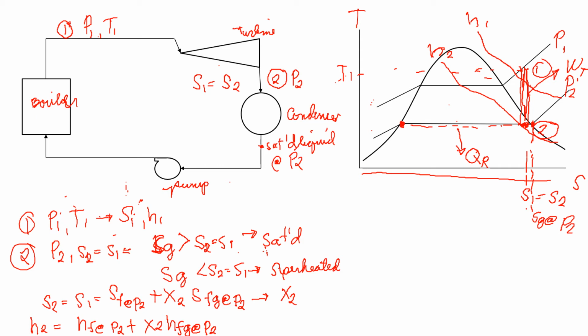What you mean by that is it should not go beyond the saturated liquid line and go to subcooled, or else you will risk the inefficiency of applying more heat in your boiler. We will be discussing about that.